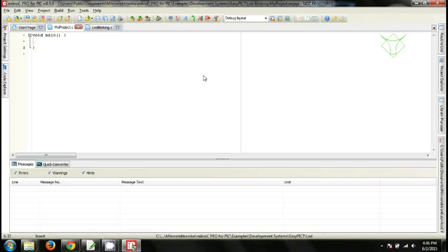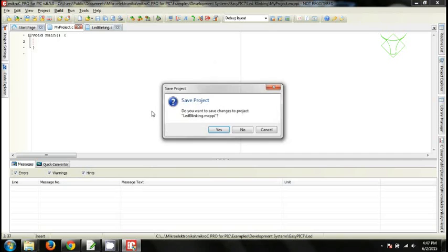Okay, and then all you have to do is build and program in case you have the hardware provided by PIC, like microC. Okay, so all we use here is this build all. Okay, and we'll use the hex code to burn. So the hex code will get generated into the same folder where this project exists. Okay, that is your Documents, microelectronica, C program developments, whatever you have selected. Okay, so I'm not saving this.